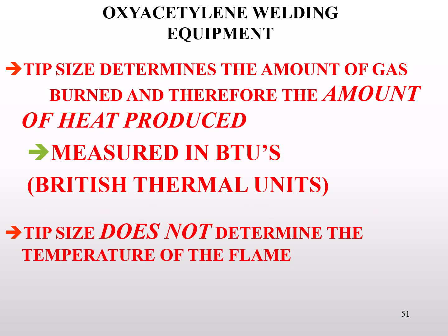This is a very common FAA question, and it's often missed. Here's the point I want to make to you. The opening in that tip determines its size, and the tip size determines how much gas can be burned. Therefore, tip size determines the amount of heat produced. Heat is measured in British thermal units, or BTUs. The tip size does not control the temperature of the flame.